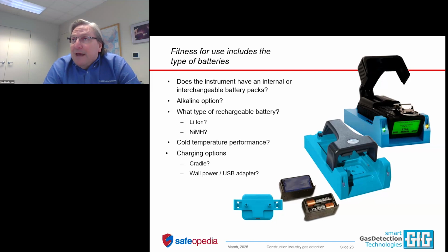If the battery catches fire, it does not even need a source of external oxygen. Eventually, as the fire grows, oxygen from the atmosphere will be sucked in, which supercharges the fire. Lithium ion battery fires are notoriously hard to put out for this reason. So, myself, I prefer to stay away from lithium ion batteries in portable instruments.